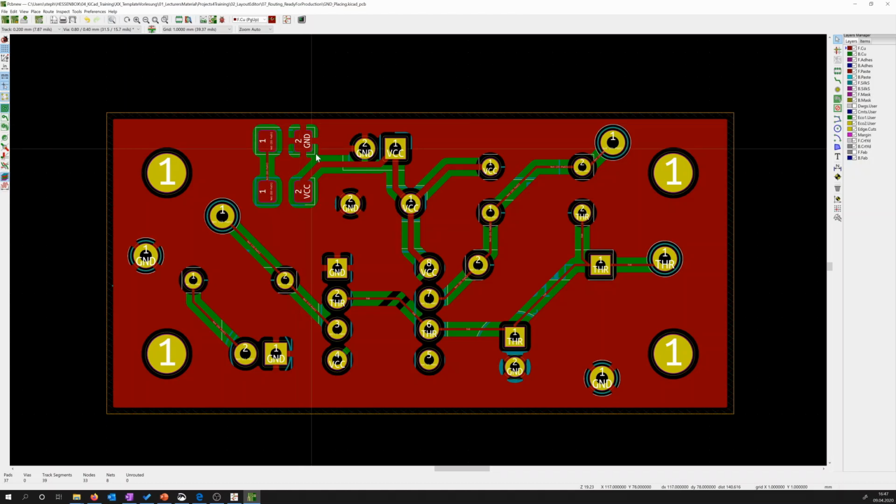Well, that's a topic of soldering, because if you completely connect this pad to ground and you want to heat up this area for soldering, and you don't have the spacing, you need a lot of power because you have to heat up the complete area, because copper is a very good heat conductor. So that's why you make the spacing, so the heat can only go from this pad outside over the small fingers, which makes it hard to heat up the rest of the copper, so you can heat up only the pad to solder your SMD.